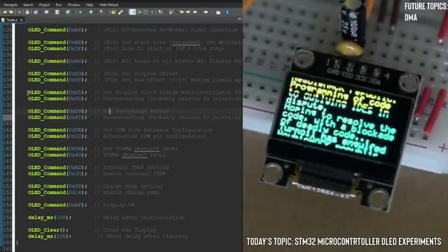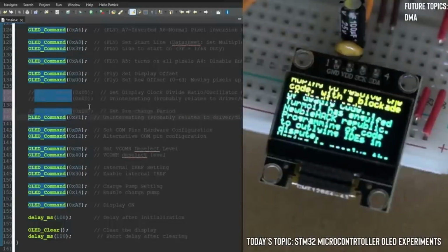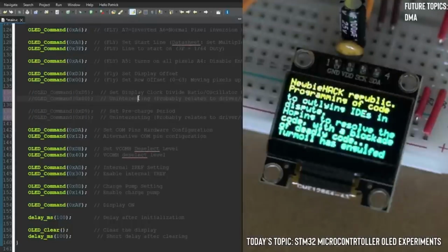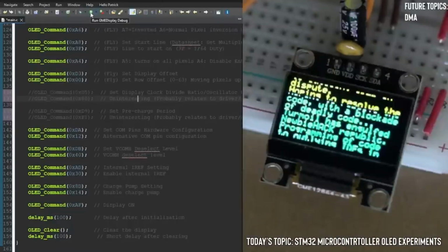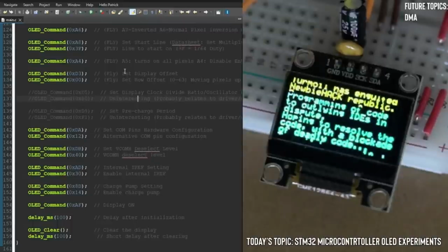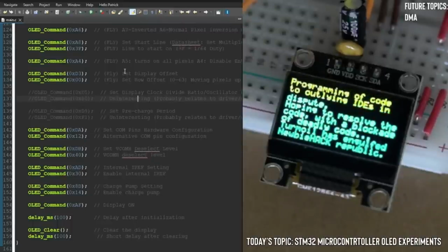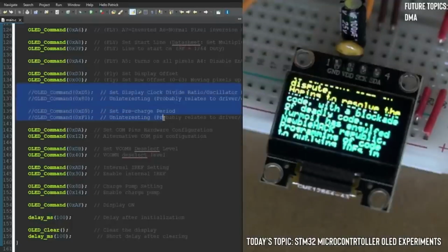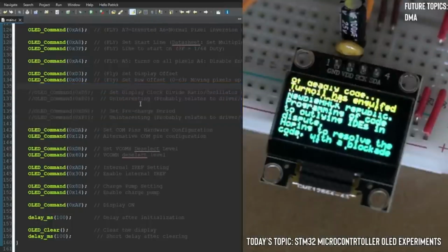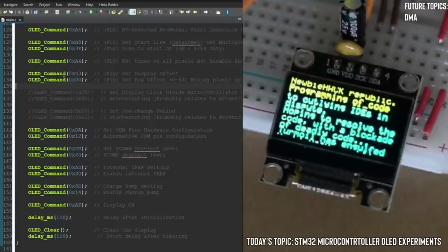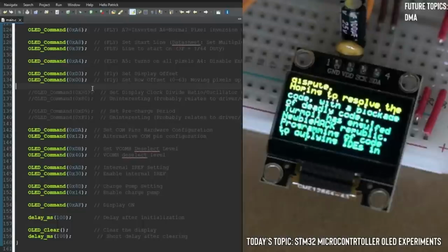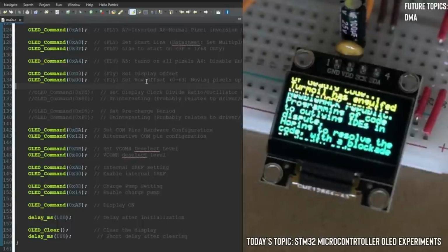Yeah, let's see if they're even needed. That's a good idea. I want to try both to see if it's already a built-in default. Let's see what happens. I like this experiment. This is a nice experiment. All right, I am running it. It is connecting, and it's successful. Okay, no change. I don't even need those. So these are not even needed. So this can simplify the program quite a bit just by taking these things out, and maybe even save a couple of clock cycles if this is a critical application and you needed to reset this often. So they're not needed.